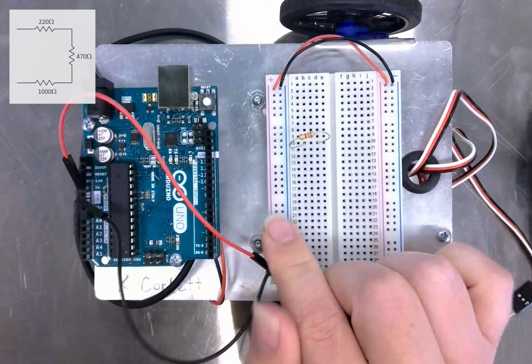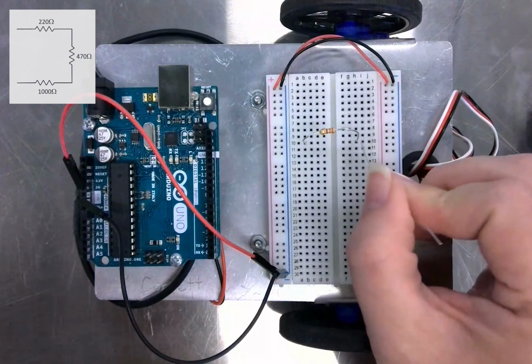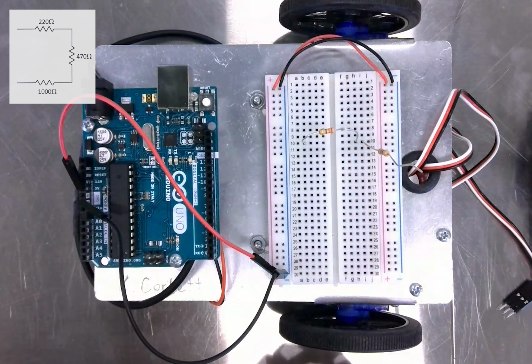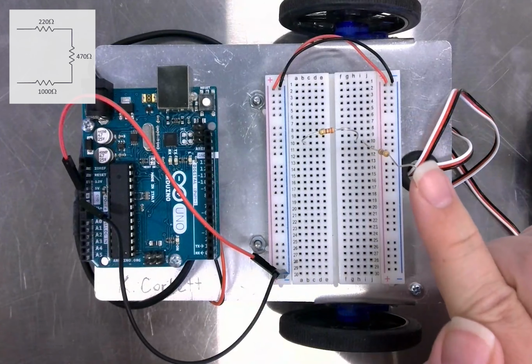So you never want to have a component of your circuit where one end and the other end are plugged into the same row. We call these individual rows nodes, and so you don't want the resistor plugged into the same node from one end to the other. So always plug it into a separate row. Now, if you're looking at the schematic of the resistor circuit, you see that the second resistor should be connected to the first resistor. So notice how I connected to the same row, but then the other end of this resistor needs to be connected to some other row. So that's helping us build our circuit.